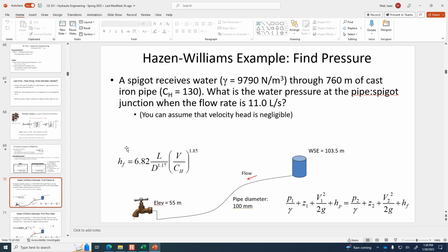That's a good question. The way that it works out is that this is not a dimensionally homogeneous equation. This is an empirical equation where someone did a lot of observations in the lab and said, oh, it fits pretty good. And so it's not dimensionally homogeneous. So the left-hand side units of meters you would not get by doing a units analysis on what's on the right-hand side of the equation. This is just an estimation. So thanks for asking that. Are there other questions?